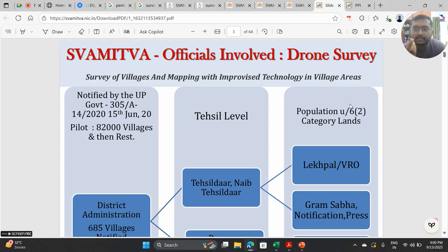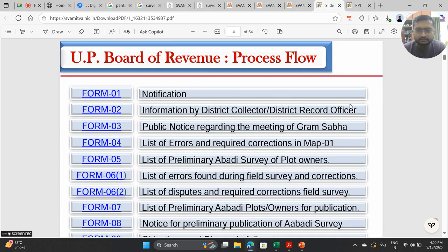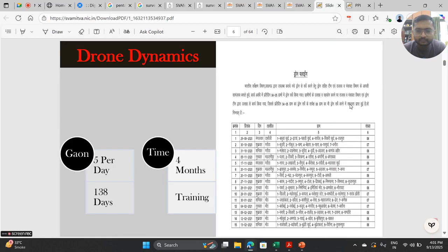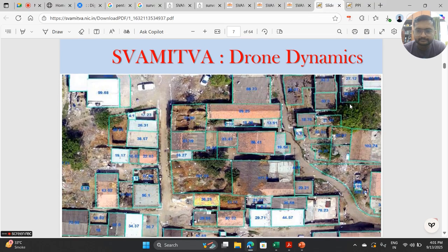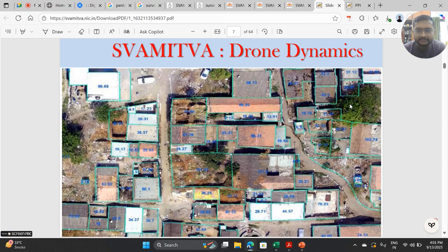So they are using the DGPS principle, where you already know the location of one point and you correct the location of another point using the given standard errors. That's why they use CORS. Means CORS works like a reference point. Yes, CORS acts as GCPs.